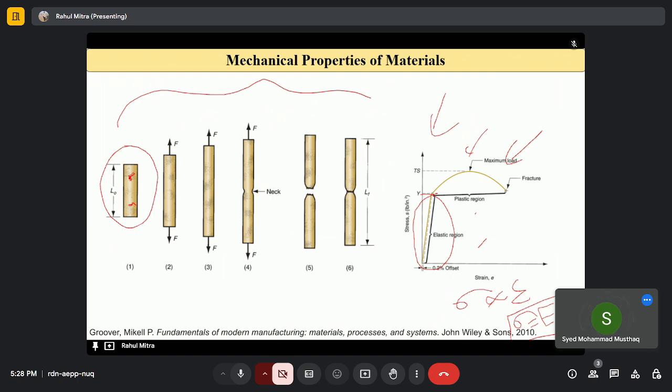So, for example, if I take from 1 to 2, if I take y as 2, then the material has reached maximum elongation up to the elastic region. If I release at this point, the elastic limit, the material again regains its original shape, right? Once I pass it, we have a yield point, where the material starts yielding and plastic deformation takes place.